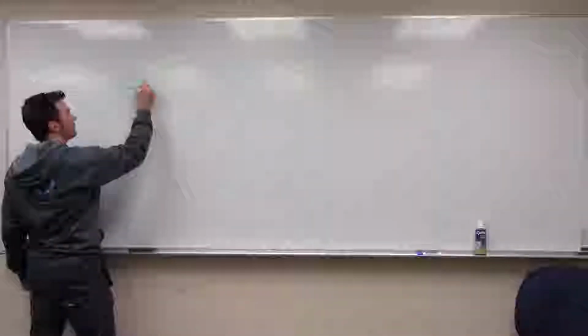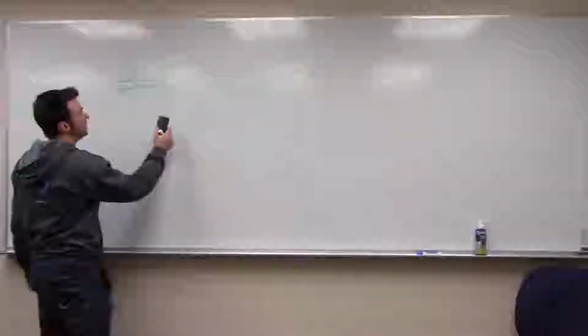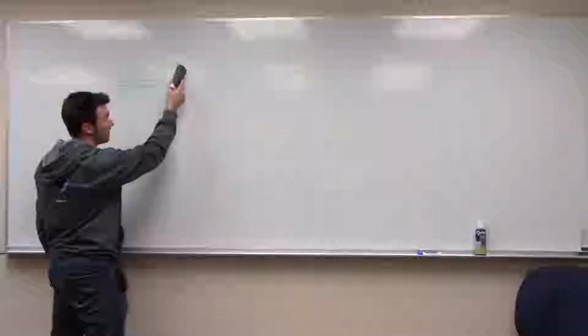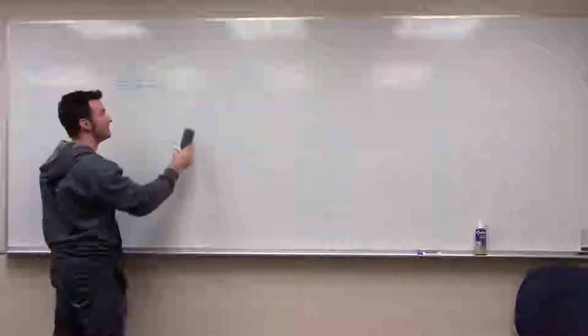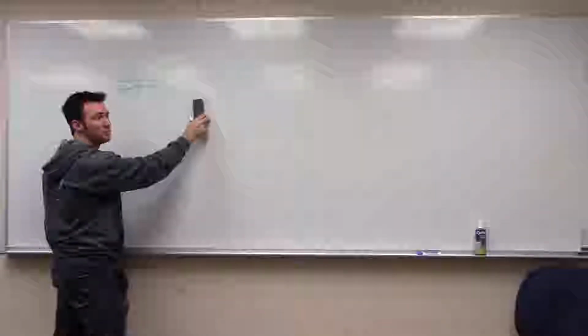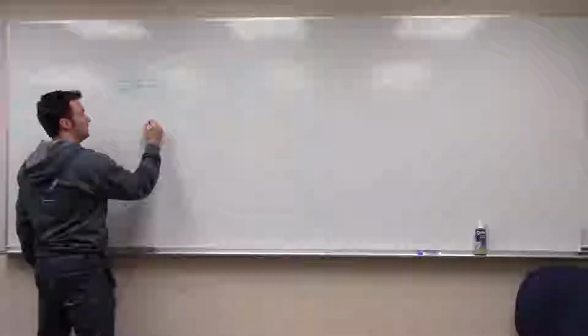Okay. And then we've got a damper here that doesn't care how far away the mass is. It just cares how fast it's moving. So if the damper is being extended, the damper is going to try to pull back on the mass. If the mass is traveling at a speed of x dot, that's the velocity, the time rate of change of x, dx/dt, let's call it v. If it's moving with a velocity v to the right, then the damper is going to be pulling it back with a force that is just c times the velocity v. Okay? We'll see that on our free body diagram.